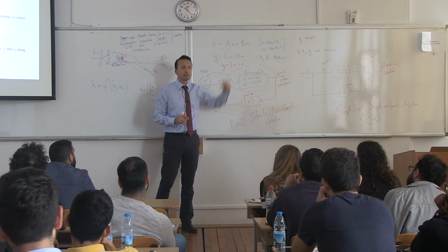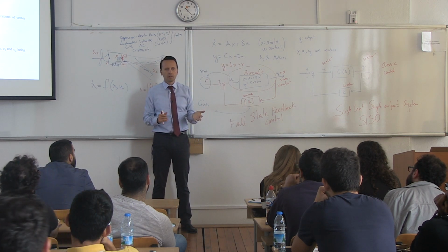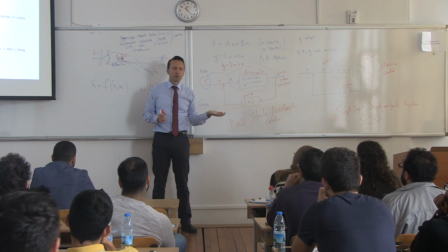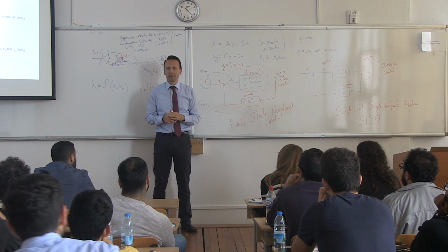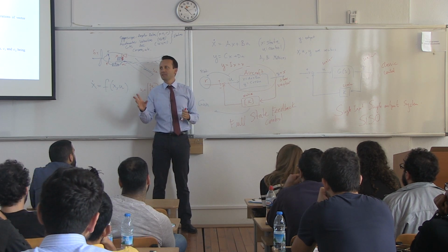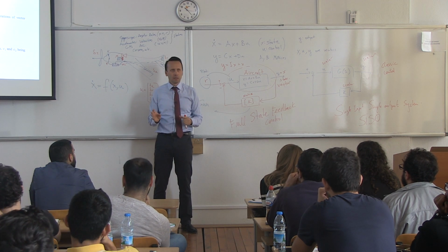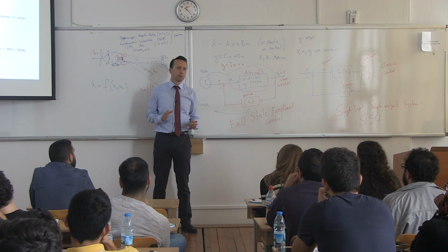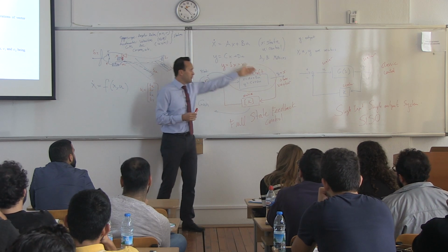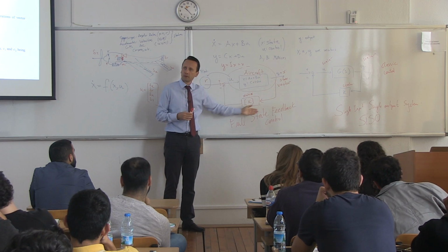You can calculate the A and B matrices. Remember how you calculate the A and B matrices? Don't remember, again, I go back to flight mechanics. We linearize things. How do you linearize it? We use small perturbations, remember? And this is all valid for one equilibrium point. So we do everything around an equilibrium point here.